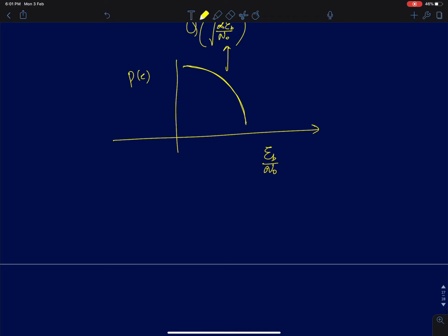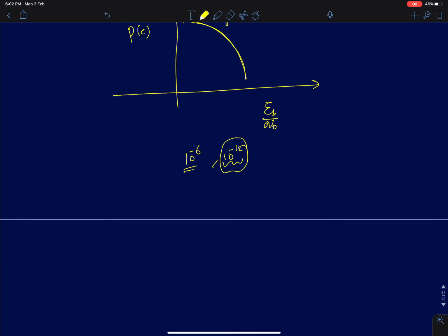So this probability of error I can achieve of the order of 10 power minus 6, 10 power minus 12, for high speed wireline data transfers between the servers in Google and all that. You need a very low bit error rate. This term is called bit error rate, PE, because it's digital communication, and this tells you approximately how many bits are in error. So when it is 10 power minus 6, 1 in 1 million bits are in error. If it's 10 power minus 12, it's 1 in 1 trillion bits in error.